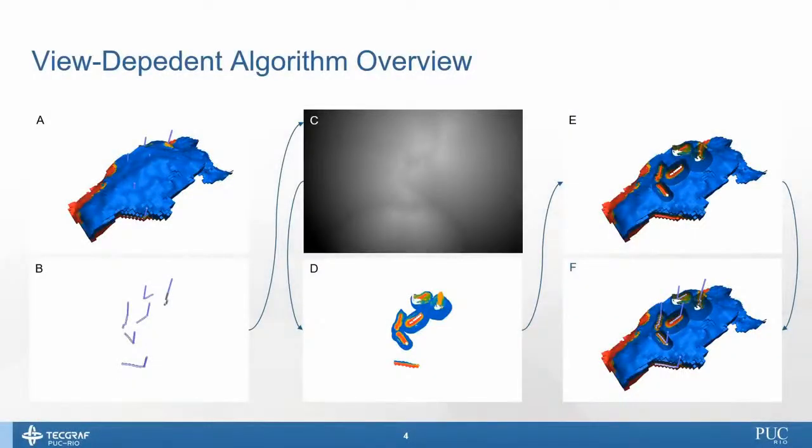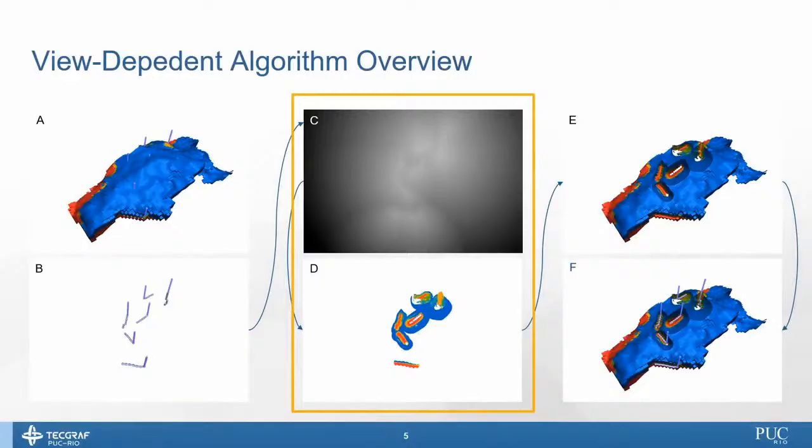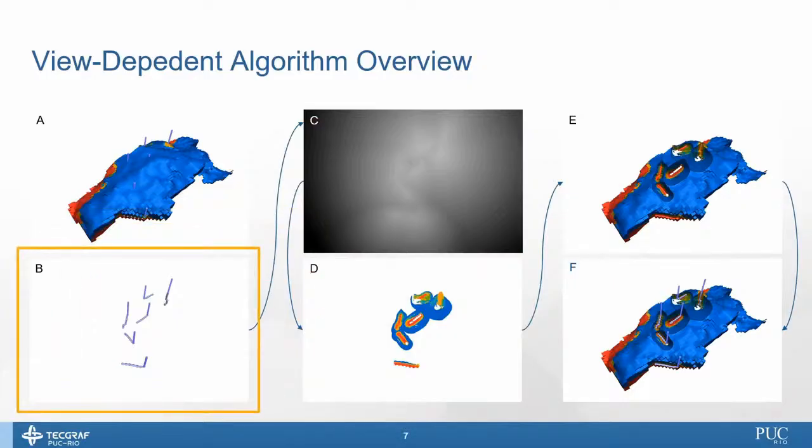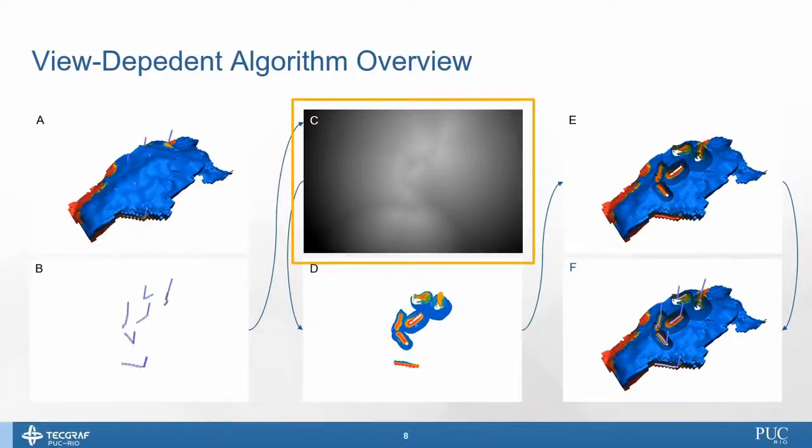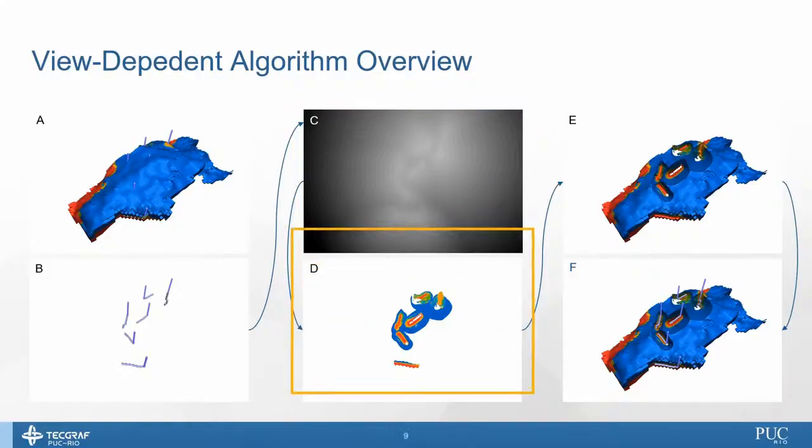In our view-dependent cutaway, we represent our cutting surface by a depth map and an intersection map with the dimensions of the frame buffer. The depth map is obtained by using the backface depth of the selected wells as input to compute a distance transform with the jump flooding algorithm. The intersection map represents positions of the cutting surface depth map that are inside the reservoir cells. This is computed with an efficient point location algorithm in GPU.